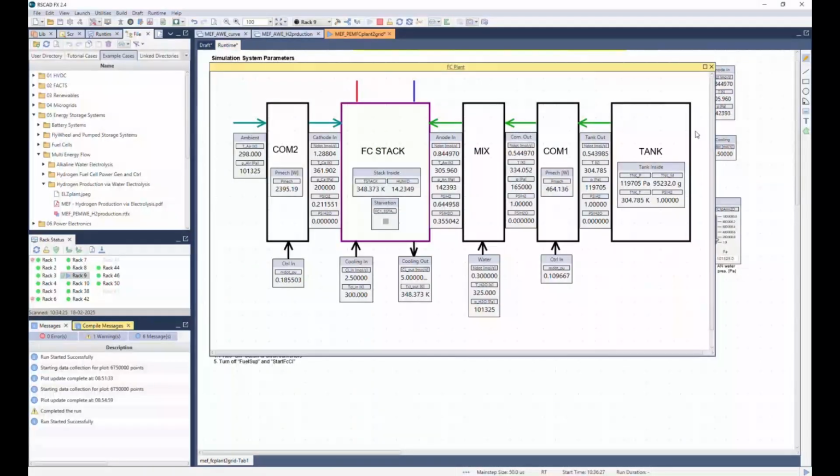If you go inside this hierarchy box, you can see the plant variable, flow properties and the component stats such as the mechanical power consumption of the compressor, stack temperature and the humidity level, and the tank pressure, mass and the temperature.